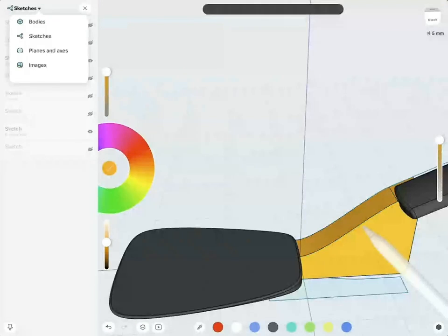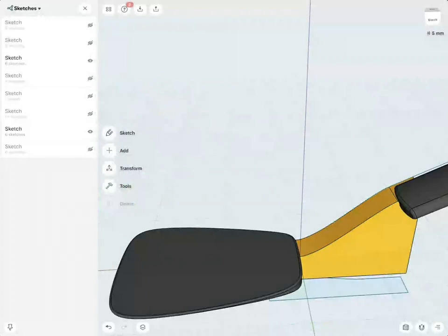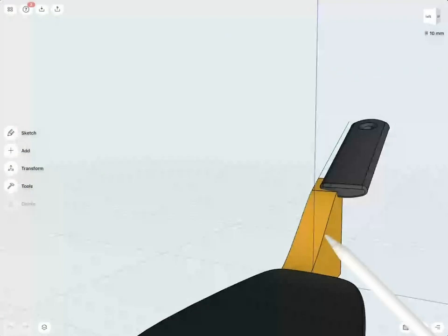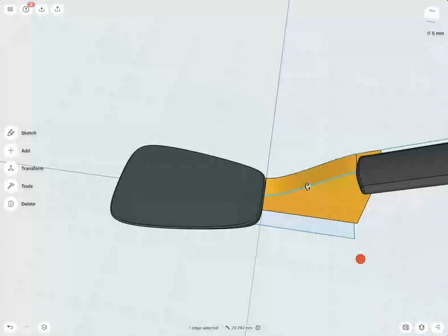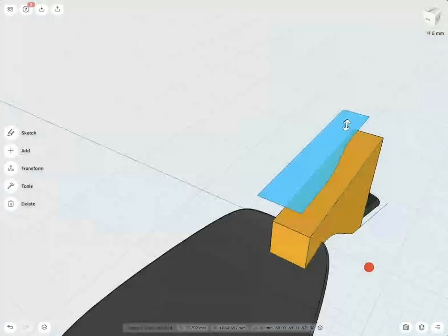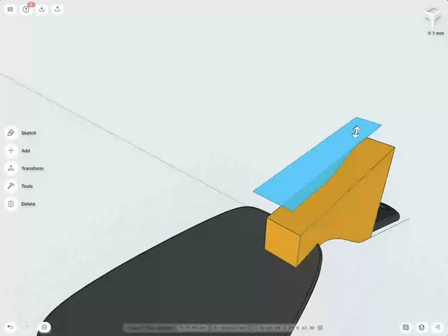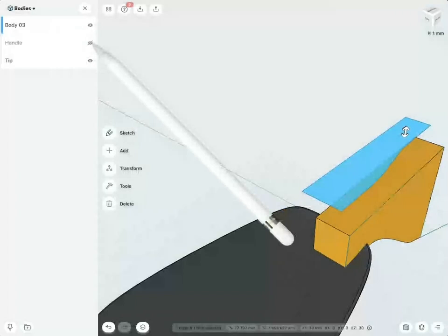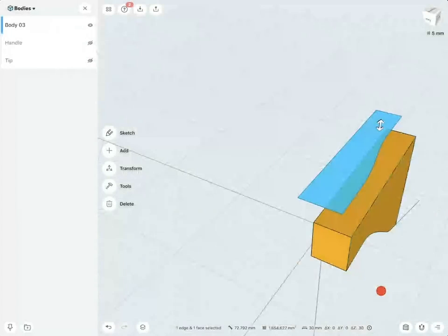So I mentioned I want to have kind of like a three-dimensional path. I extrude this one out, and this edge now I want to bend or curve. And I simply do this via this sketch. So to make this operation work a little bit easier, I hide these two other objects.